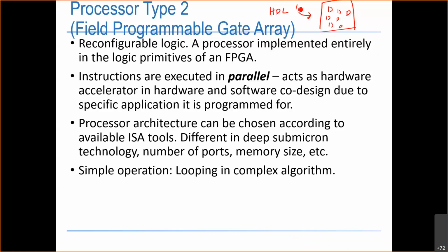And what you do is that you download the circuit to this FPGA board or FPGA chip, the field programmable gate array chip. So the configurator is going to build the connection to represent that hardware description. So if your hardware description is an adder, an 8-bit adder, for example, the hardware in this FPGA will be connected to represent that 8-bit adder. So what you're going to get is a digital circuit on the FPGA, which is very, very fast.